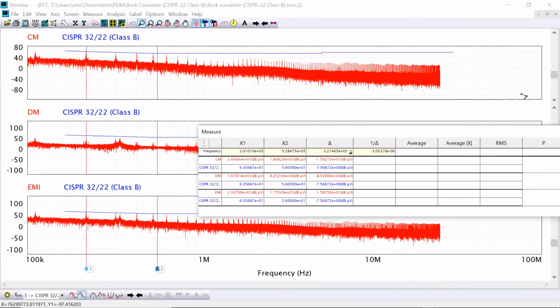once it is completed, we can inspect the CM, DM signals to make sure they are below the EMI standard level. And here, this is exactly the case. However, if we still see some inconsistencies, we can tune the parameters from the user specification input. Now my circuit is in total compliance with the EMI standard and it fulfills the user specification at 100%.